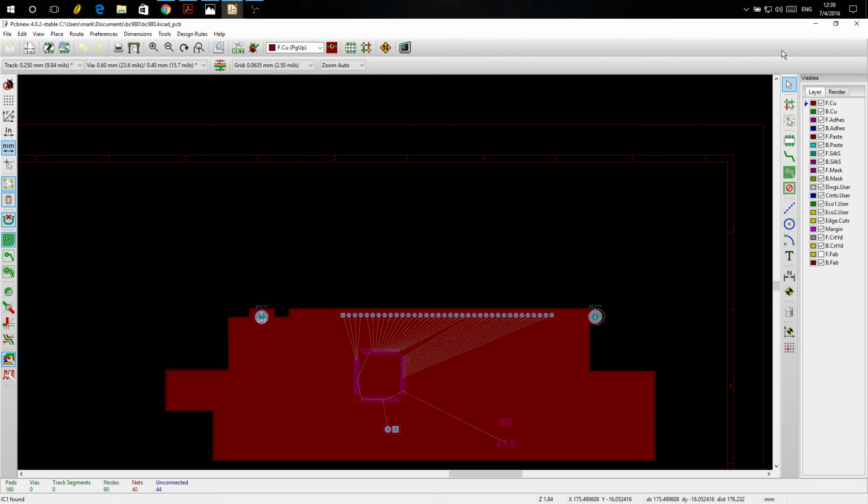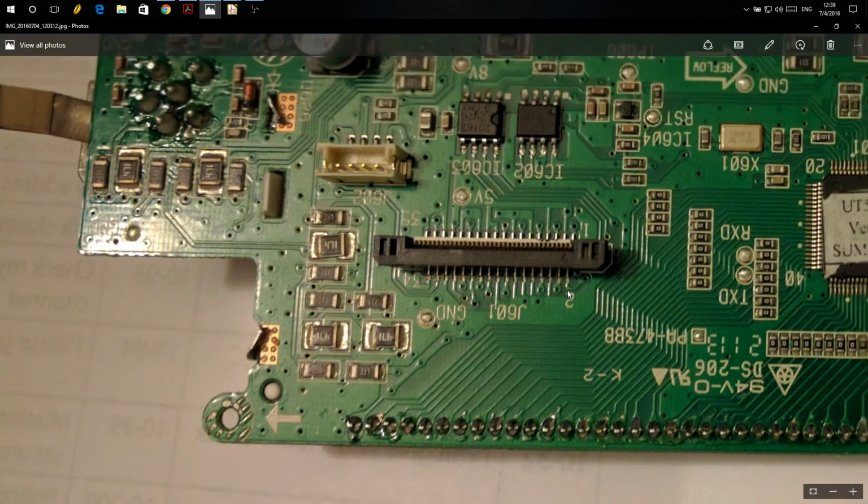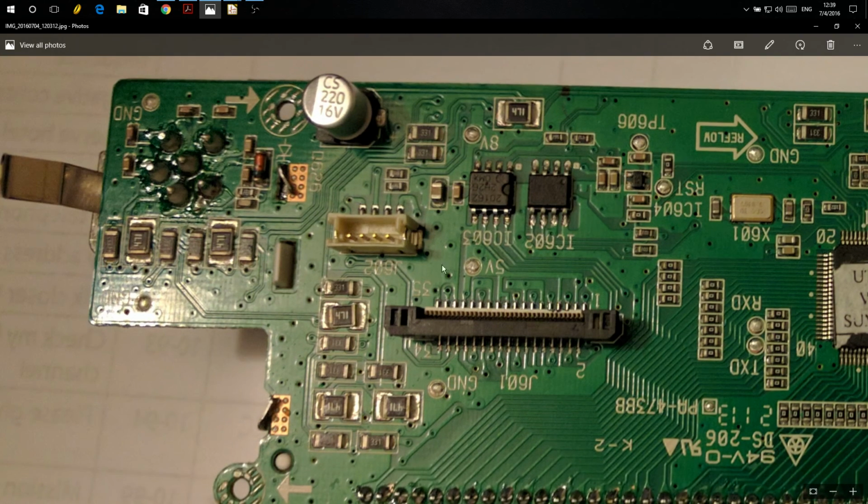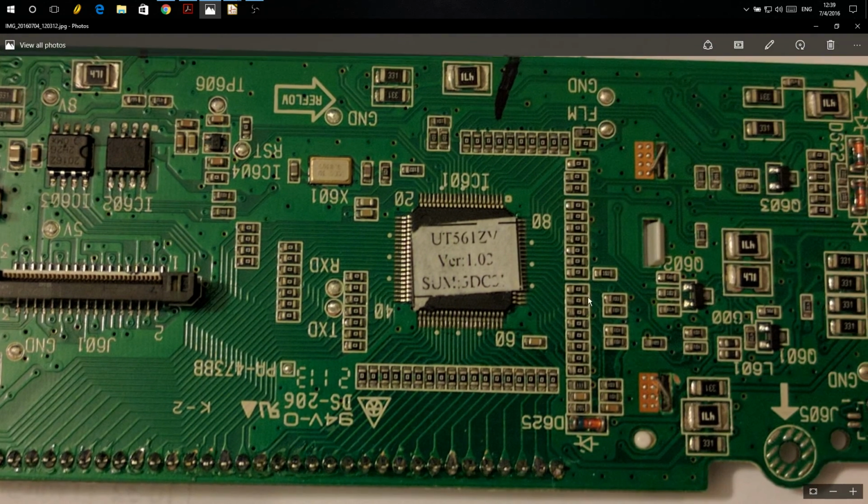A lot of component placement needs to be done. I need to reverse engineer the illumination, the diode positions for the LEDs. Those all have to be done. Basically, this is the hardest part. I have to sit here with a board, and I have to mark out and measure precise locations to the centers of these mounting holes. With some calipers, I have to measure everything out, everything.